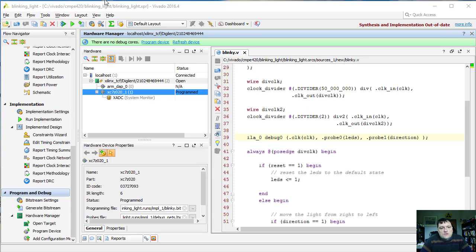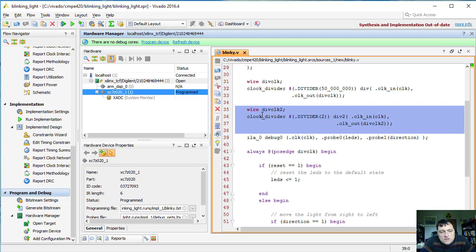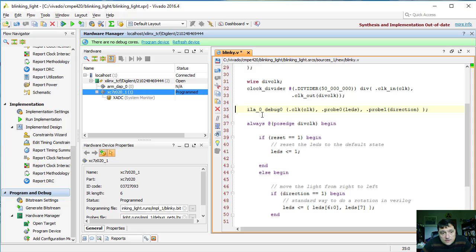So it turns out the Xilinx tools have a limitation on the ILA clock, and it has to be at least as fast as the JTAG cable. In this case, I'm going to go ahead and take out the clock divider. I was unaware of that limitation.